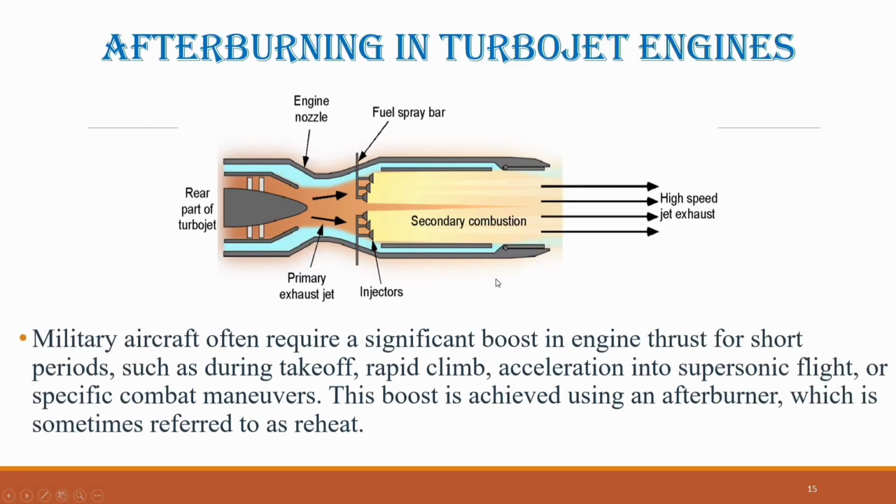Afterburning in turbojet engines. Military aircraft often require a significant boost in engine thrust for short periods, such as during takeoff, rapid climb, acceleration into supersonic flight, or specific combat maneuvers. This boost is achieved using an afterburner, which is sometimes referred to as reheat.